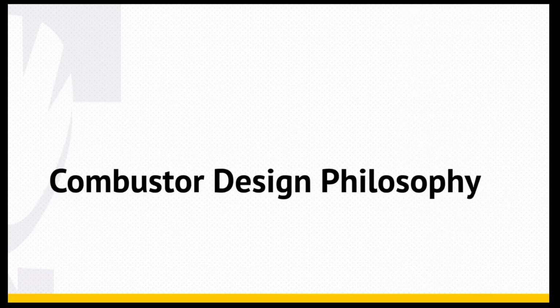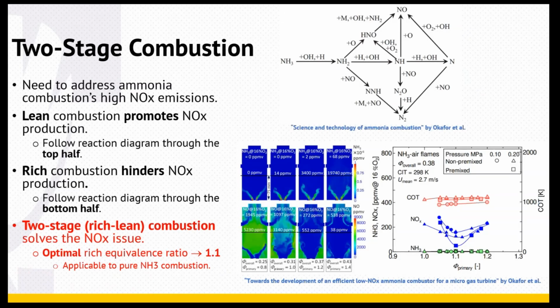Now I'm going to get into a little bit of the design philosophy I was following with my combustor for this engine. So number one, when focusing purely on pure ammonia combustion, we need to address the high NOx emissions. And one of the strategies for pure ammonia combustion that people have found works the best is to utilize two-stage combustion.